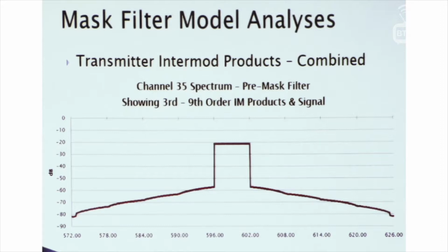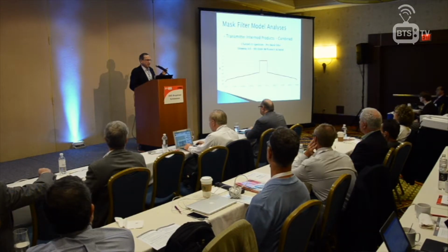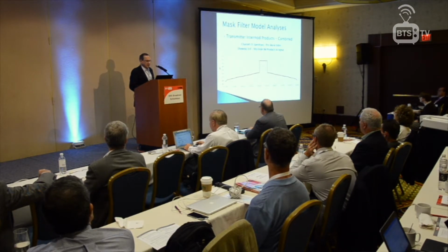But channel power is up here, and because we're using a 50 kilohertz bandwidth, think of it as a spectrum analyzer resolution bandwidth, in order to look at this, the flat top of the signal ends up 20.79 dB below that. If you add up minus 20.79 dB of power 120 times, you're going to get 1. It'll come to unity. And that's up here at 0 dB. So that's why we have that separation.